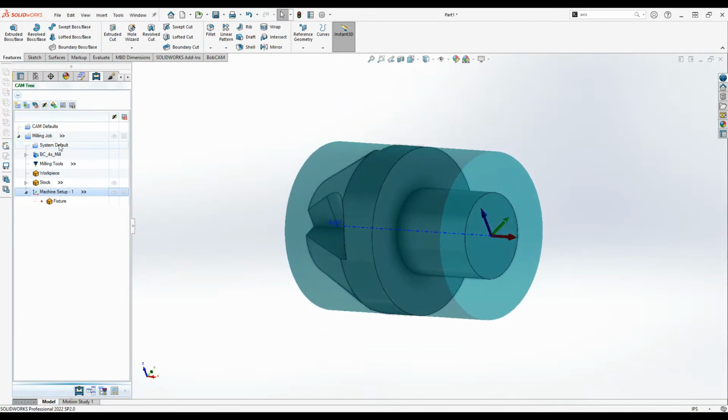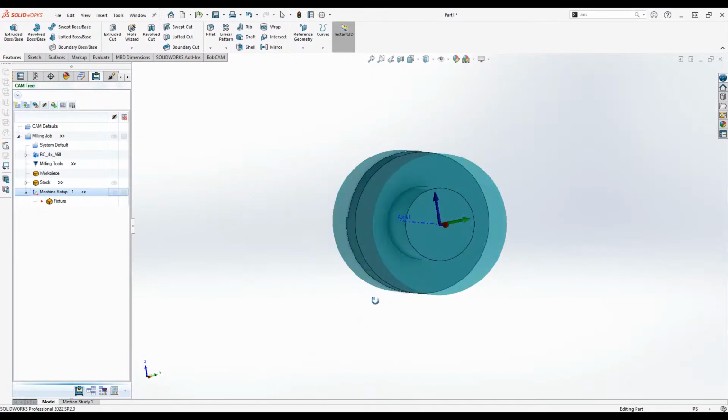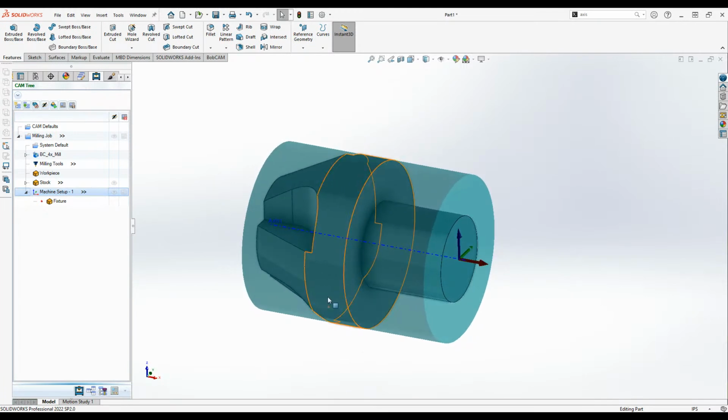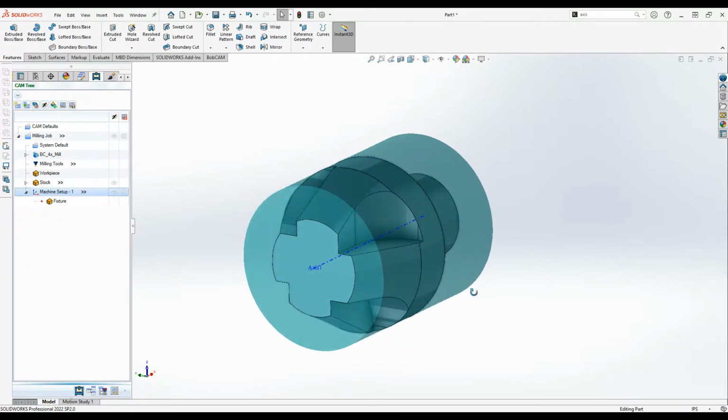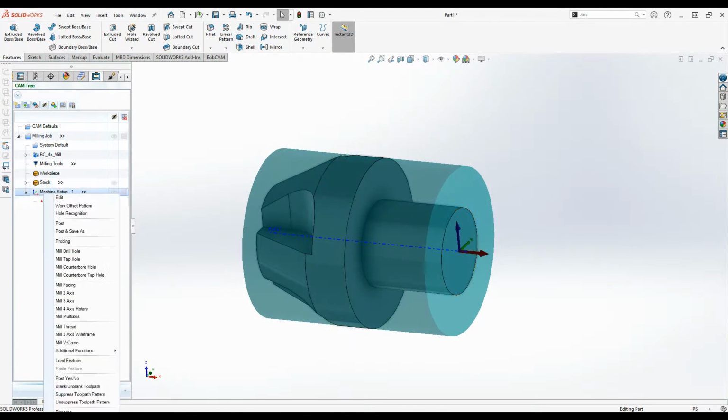So what I have right now is the part on a four-axis job. I have a zero on center line, and what I want to do is machine the part. Do I need an index system to start machining? I would believe so. Unless you have the open pocket setting, since from looking at it, it looks like you have the Z axis pointed specifically to where you don't need to index to start. Right. So if your Z is aligned with your part, technically you can just start loading toolpaths.